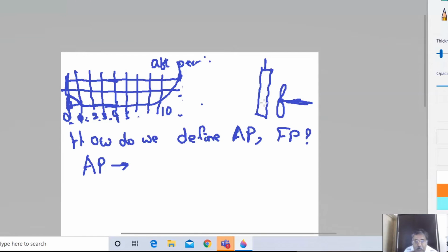So in front of the propeller or behind the propeller, whichever way you are looking at it, you will have a rudder like this. Now the rudder will have a center, and this aft perpendicular is defined as going through the center of this rudder stock, basically the centroid of the rudder. So the line, the aft perpendicular, actually is defined as going through the center of that.